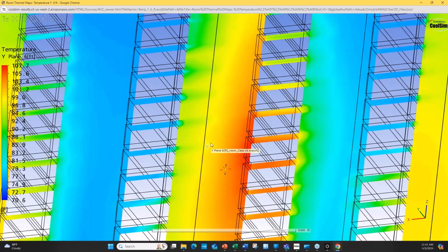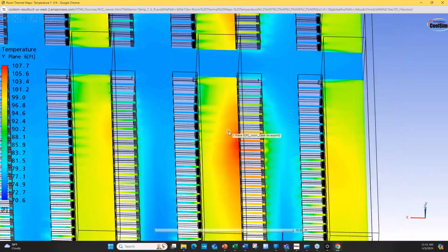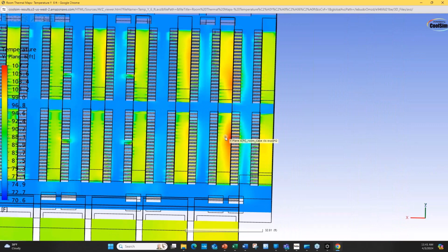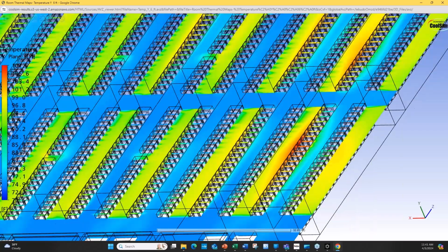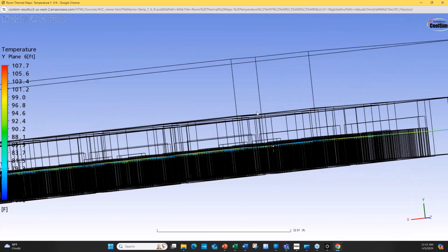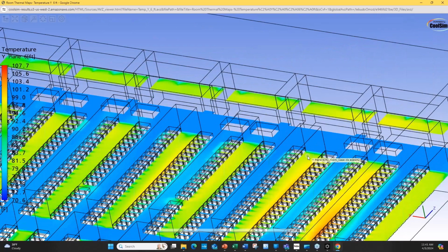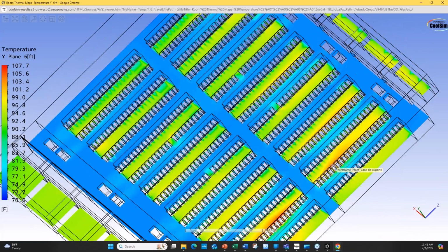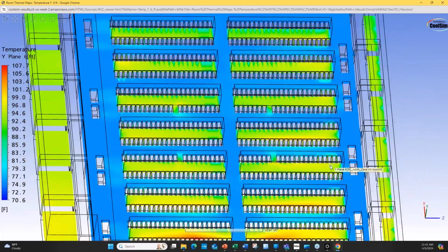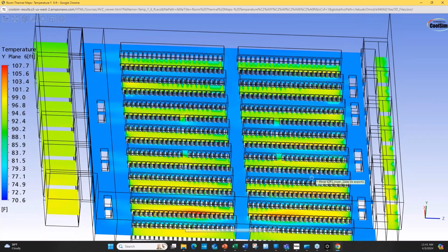So I think, Paul, that this demonstrates the importance of air management, because this is nothing else than an air management issue. You haven't tightened up your equipment rows. So what we are preaching in our training program is air management is a prerequisite before you do other energy efficiency measures in data centers. Exactly correct. Unless you have proper sealing on these designs, and these designs are critical.